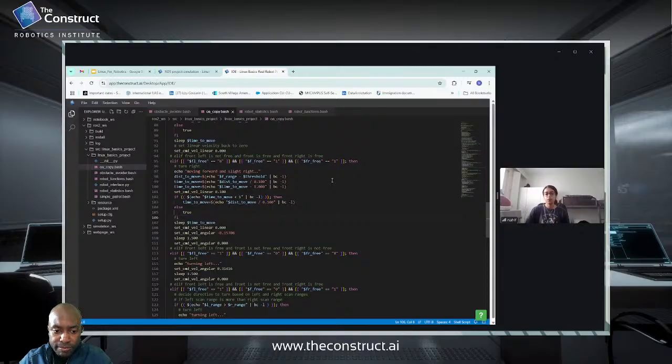Yeah, so I tried a lot of things. The first thing was actually reducing the speed, but reducing the linear speed is not a great idea at all because the speed is quite slow to begin with. So then I decided to play with the angular velocities. Like I mentioned, I tried larger angles, like 90 degrees. I tried smaller angles. The issue with going even smaller than 14 degrees at the minimum, which is what my current script uses, is that now it needs a lot more iterations when it's not in a super blocked position. So it takes a little bit longer to decide, and also to complete a full track. It will have to turn right maybe 3 times in order to finally avoid a wall. So yeah, I bet I could fix this issue if I did a little bit more testing. But for now, I think it's not too bad.